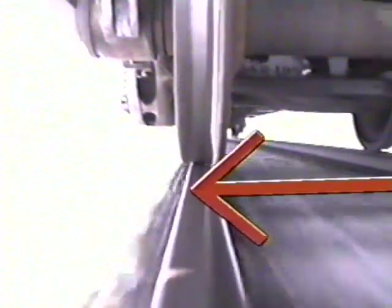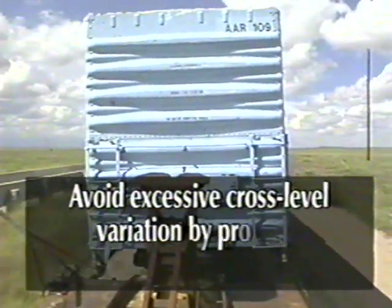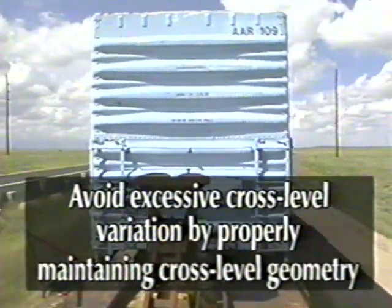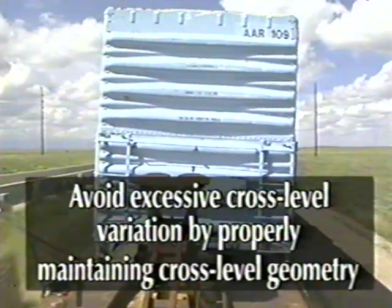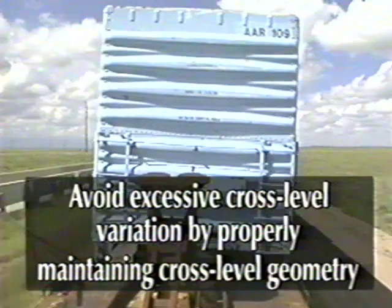In this case, a small lateral inward force to the opposite wheel in contact with the rail can cause a wheel set to climb the rail. Excessive track cross-level variations should be avoided by properly maintaining the track cross-level geometry, especially in jointed rail track.